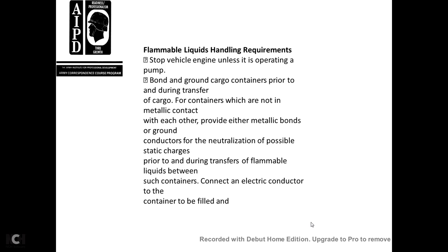Flammable liquids handling requirements. Stop the vehicle engine unless it is operating with a pump, and bond to ground the cargo containing the liquid during transfer of the cargo. For containers which are not in metallic contact with each other, provide either a metallic bond or a ground conductor to neutralize possible static charge prior to or during transfer of the flammable liquids between such containers.